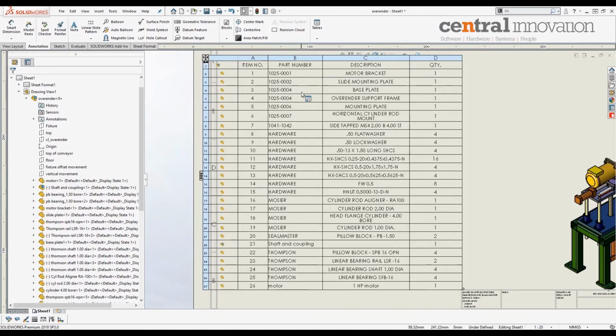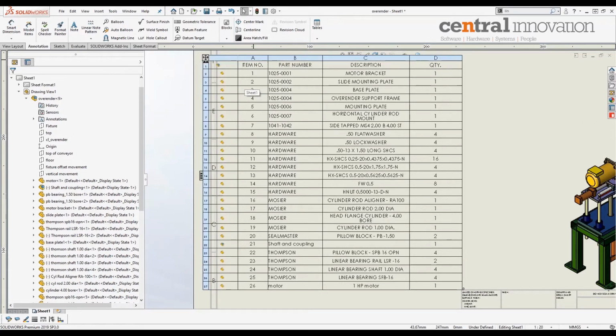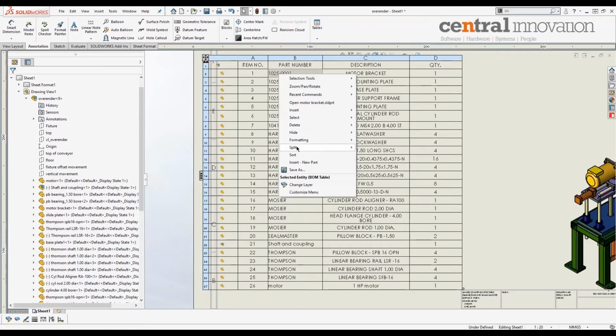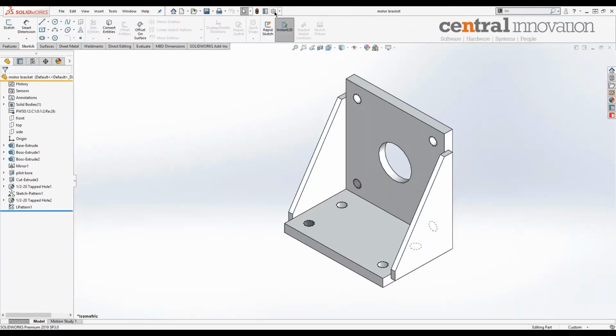Another thing is how the part numbers are listed. The information populated in the part number column by default goes to the document name of the parts, but in this particular bill of materials it has been set up as custom information, where users normally want to go with either a specified number or the vendor name or whatever. So this can be specified.